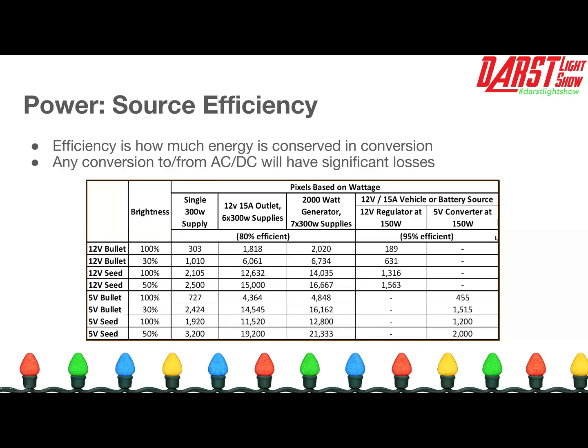For me, I can handle more than 10 of these because I've run distributed power throughout my truck and I have multiple power ports in different areas. But on a typical vehicle, like your cigarette lighter style aux power, those are generally going to be limited at about 10 amps. So you'd only be able to run one of these off of that.